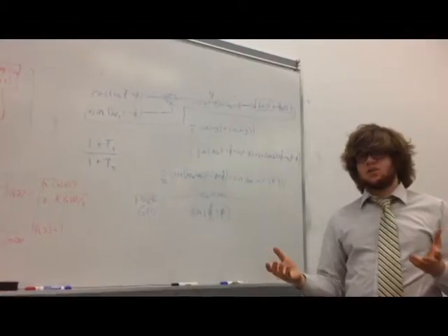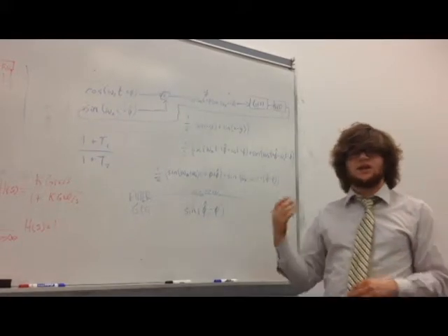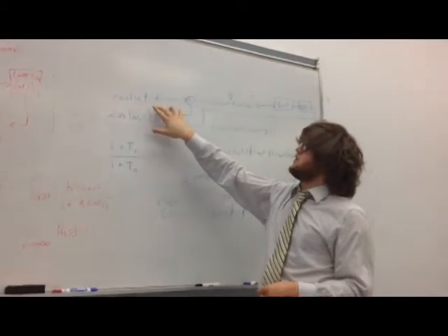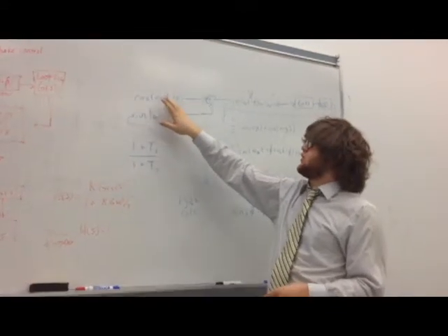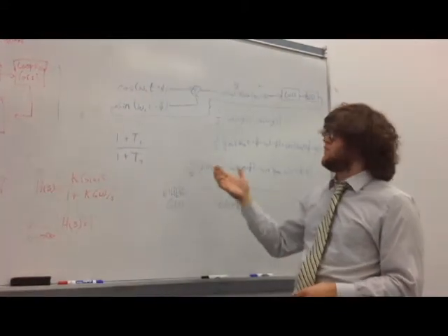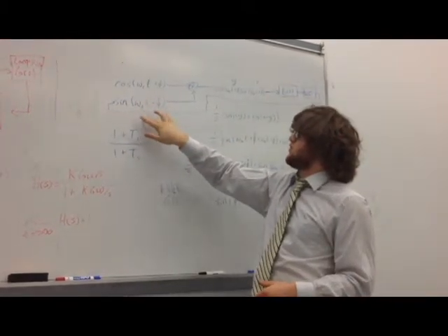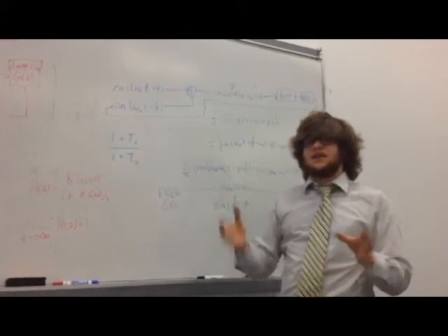So now I'm going to talk a little bit about phase lock loop in the analog domain. We're going to have some sort of reference signal at a particular frequency and phase, and the output of the voltage-controlled oscillator is also going to be at some particular frequency and phase, but exactly 90 degrees offset.